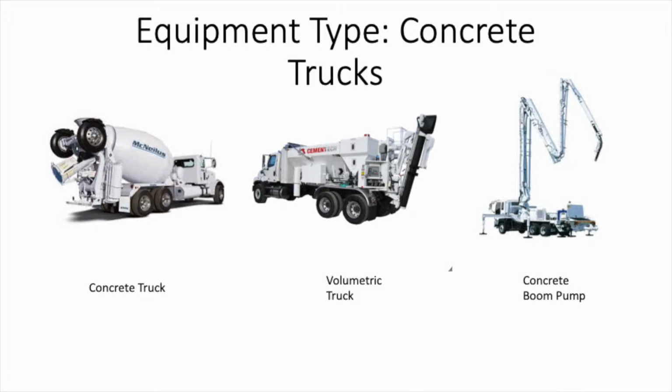Now the second type of truck isn't as common, and that's the volumetric truck. They're typically a little more expensive, but the advantage you get with a volumetric truck is that you can mix the material upon arrival. So if your travel time is super far away, or maybe your job's in the mountains somewhere where there's not a convenient concrete plant nearby, you can utilize these trucks, and they'll mix the concrete on site with aggregates and additives that they have on board their trucks.